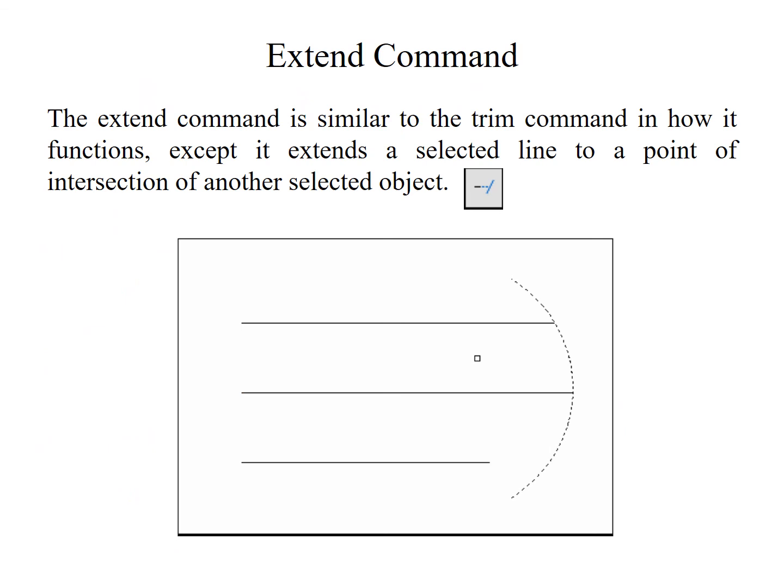Extend command. The extend command is similar to the trim command in how it functions, except it extends a selected line to a point of intersection or another selected object.